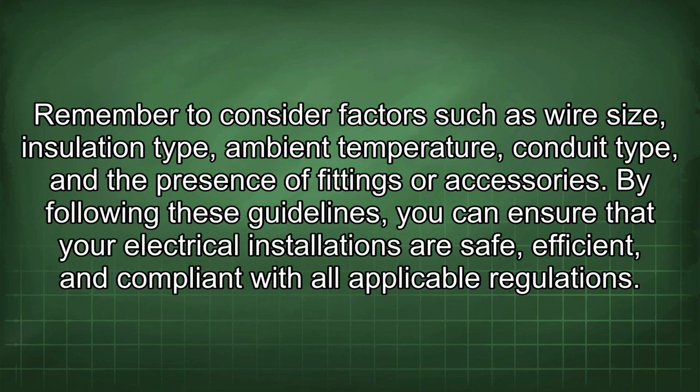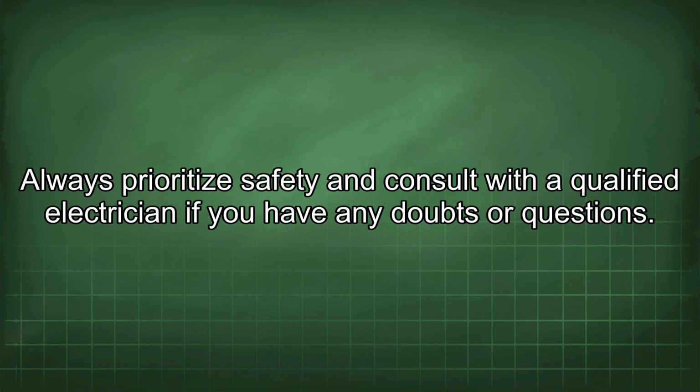Remember to consider factors such as wire size, insulation type, ambient temperature, conduit type, and the presence of fittings or accessories. By following these guidelines, you can ensure that your electrical installations are safe, efficient, and compliant with all applicable regulations. Always prioritize safety and consult with a qualified electrician if you have any doubts or questions.